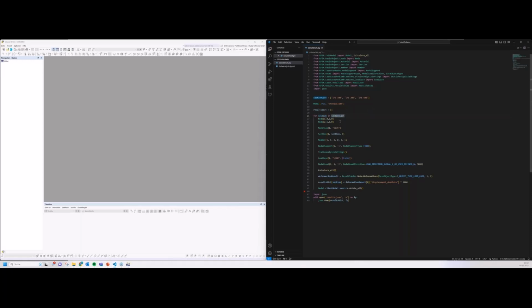The first thing to do is to define some nodes. So we have a first node here, which is at the origin, X, Y, and Z equal to 0. And then we have a 5 meter long column in that case. We want to assign a material. Here it's a simple steel S235. And this material is assigned via this text and a material number.